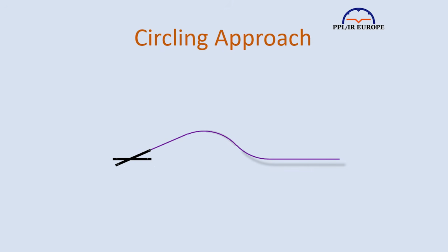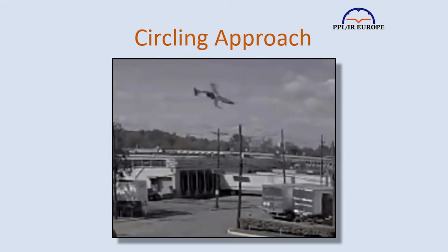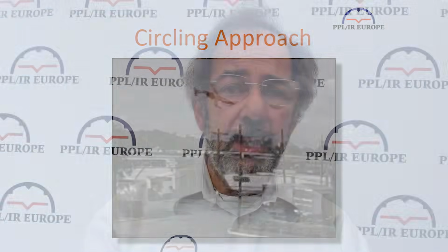An element of confusion I often hear is that because they're called circling, they entail a 90 or even 180 degree turn. This is not the case. A circling approach may only be an adjustment of a few degrees, and there are several examples of executive jets mishandling apparently quite small course changes but going unstable. It seems that a common cause is a lack of recognition of the dangers just because the turn is small and not considered a challenge.